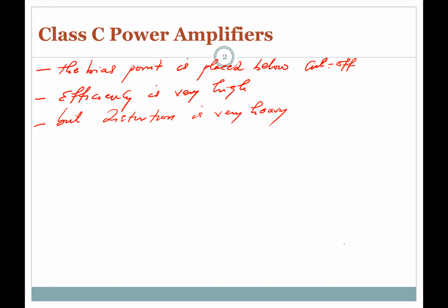It is, however, commonly used in high-frequency sine wave oscillators and certain types of RF amplifiers, where the pulses of current produced at the amplifier output can be converted to a complete sine wave of a particular frequency by LC resonant circuits. So very often you wouldn't see a class C power amplifier being used, because of the issue of high distortion, even though it promises very high efficiency.